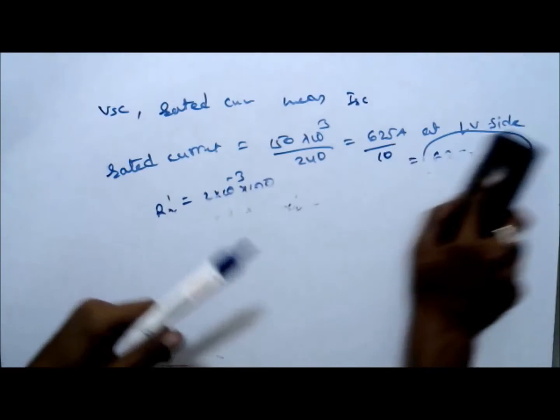This is somewhat tricky because here we have taken a 3-phase transformer. This is taken from the Bimra book. Here we first have to convert all the values to per phase quantities, because we conduct the test in 3-phase only, but the analysis will be per phase.